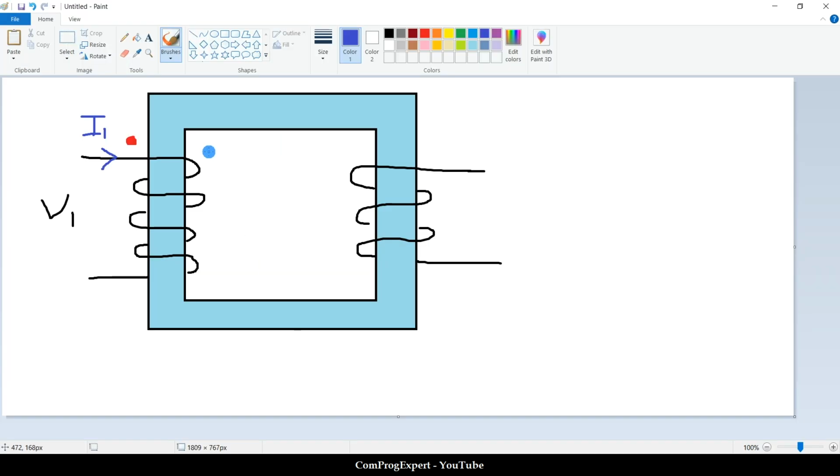In this case, what is the right direction of the field generated by this coil? It is in this direction, right? So this is φ1. And we have this equation, the integral of H dot dl is equal to the summation of N I for all coils, the summation of magnetomotive forces.